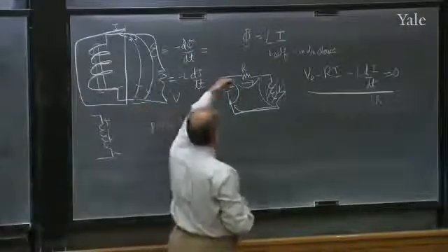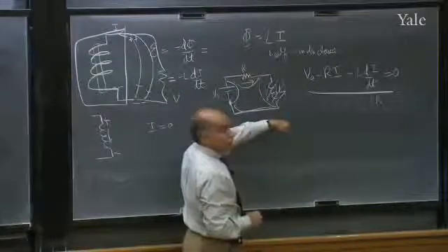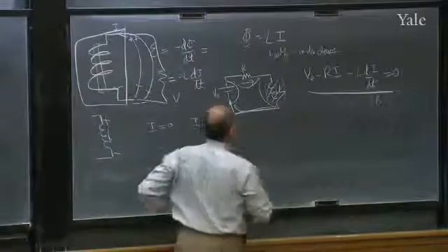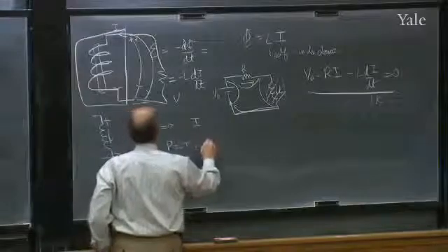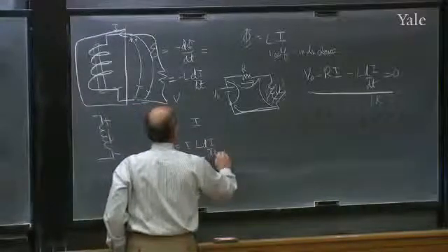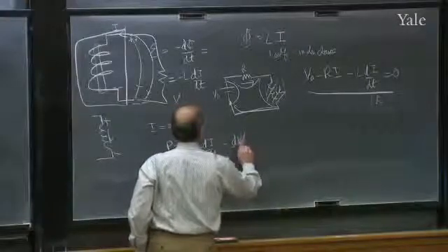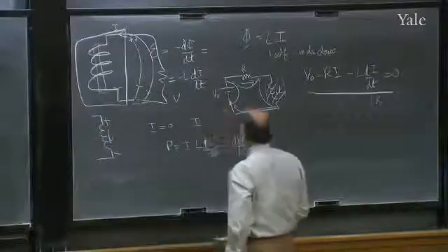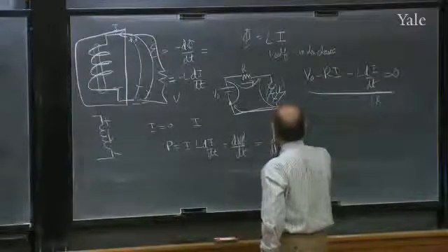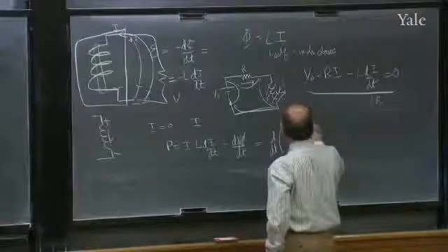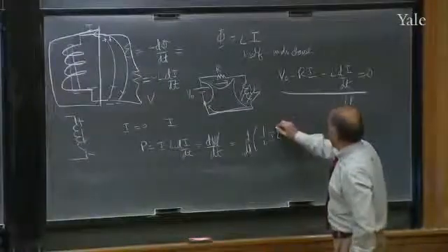Because when you start driving the current, it's opposing you with a voltage L di dt, and you're ramming it up in spite of that opposition, so that the work you do, the power, is I times L di dt, which, if you like, the rate of change of energy. But I times L di dt is d by dt of 1/2 L i squared.